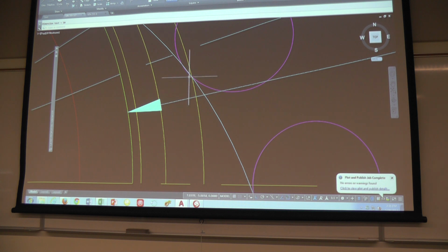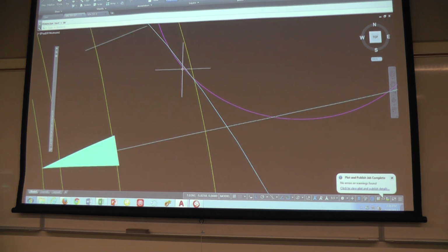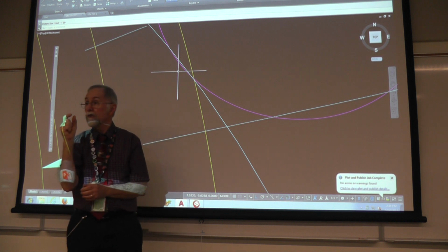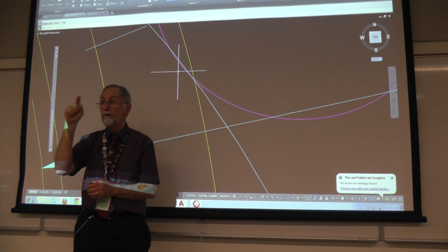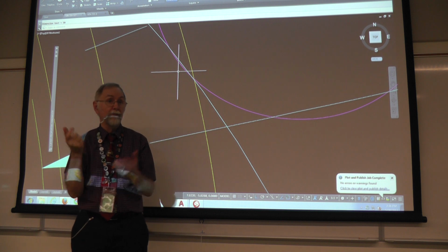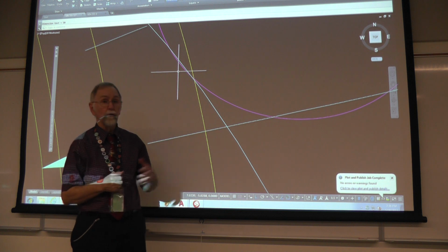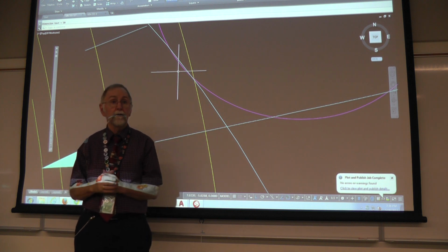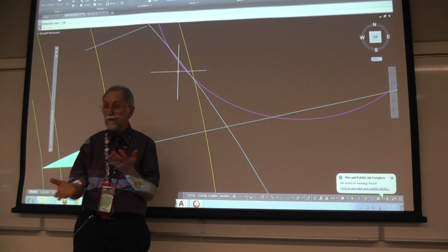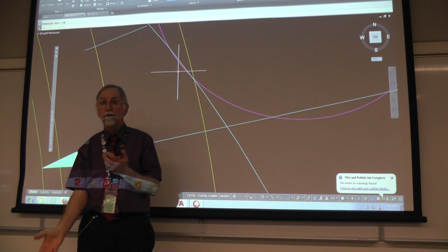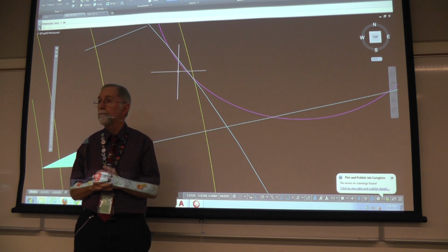Of my vertical distance. So you can see that this profile does not exactly hit the bottom of the cam, but you know what? That's a pretty insignificant amount in thousandths of an inch, and it's not that critical, because once I get that profile, again, it's the tool that I have to work with. It'll do as close as it can to tangency. Some of them are closer than others, and it's gonna be fine. It would do what I need to do. It would actually do the harmonic motion rise, the dwell, and the modified uniform motion drop, and it wouldn't be that significant to create the drawings.